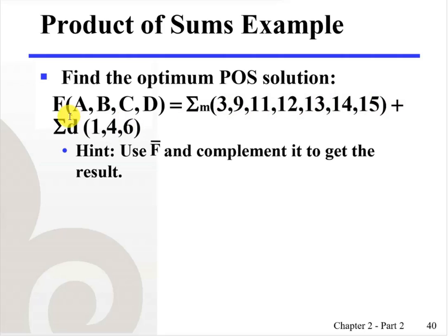And the don't care is the condition where we don't care about the function's output for these specific inputs. So we don't use the function's output. To solve this optimization problem, or simplification using a K-map, we form the 4x4 K-map and form the grouping of the cells at these locations and include our don't care conditions, X's.